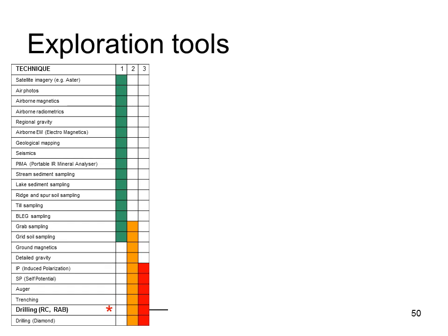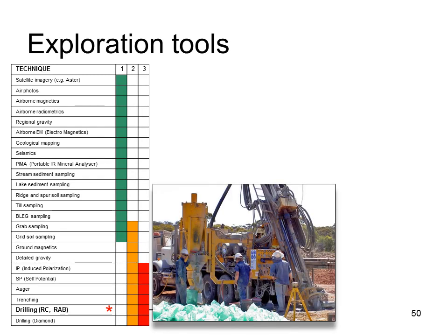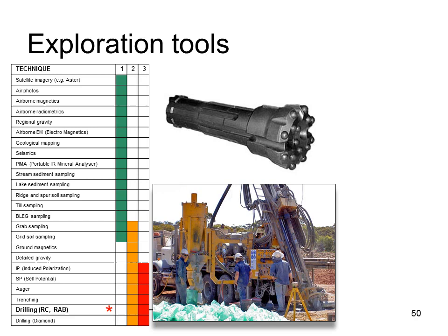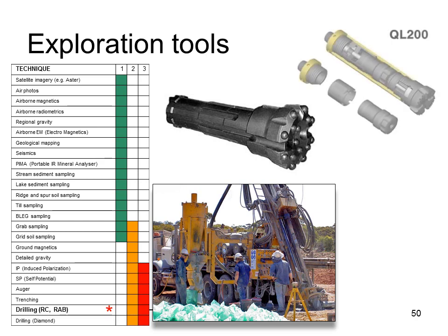Drilling is an indispensable method for exploring the third dimension. The drill rig is sometimes referred to as the truth machine. There are a variety of different drill techniques. Reverse circulation is one of the most common. An RC bit is solid with tungsten buttons. It's attached to a hammer and double-walled drill rods. A compressor blows air down the outer tube, and the drill cuttings are blown up the inner tube. Cuttings are collected from the cyclone, the big yellow cone at the bottom left of the picture.